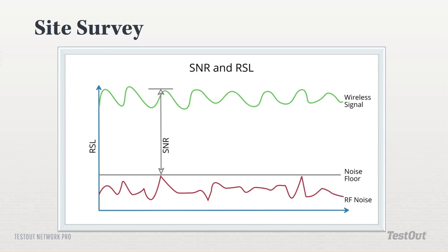So you can see from this exactly what's going on. It can also provide a reading of the noise floor, especially if you have a basement and concrete that you need to go through. So you need to identify the minimum signal-to-noise ratio the clients need to receive the signal level parameters, or the RSL.